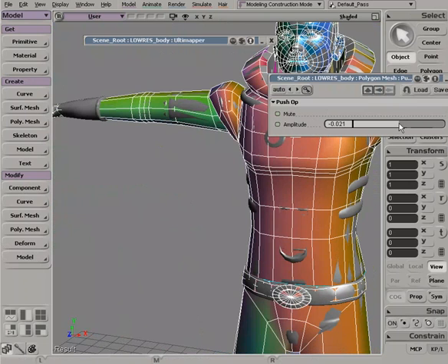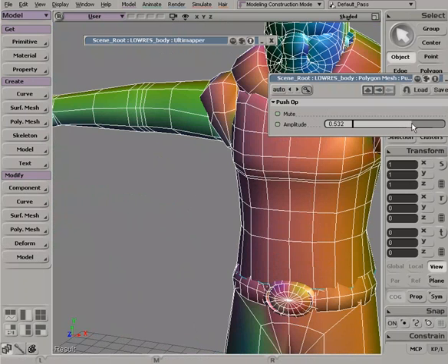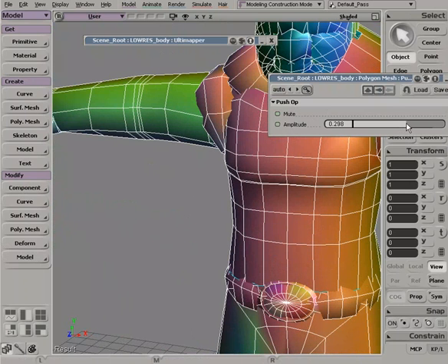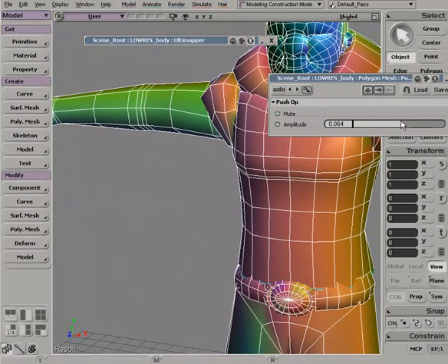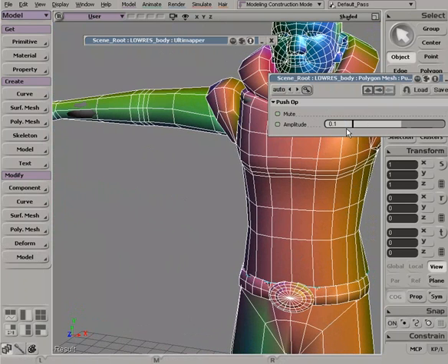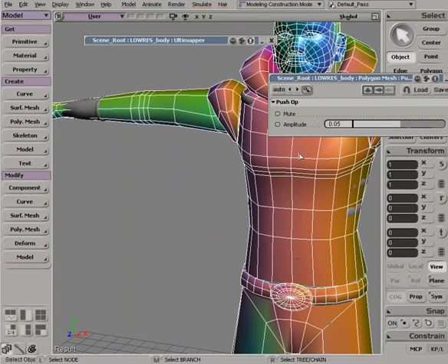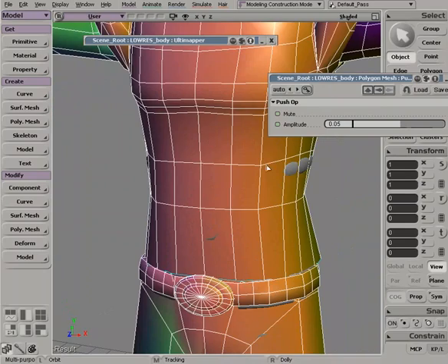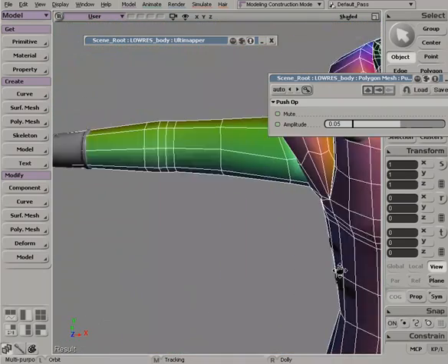With this Push Deformer, what it will do is pretty much inflate your mesh. You can see how that's slowly inflating this. So what I can do is just give this a really low value, like let's say 0.1. That's actually probably too much. Let's try 0.05. Just enough to be able to encompass pretty much all of these areas of detail that we're going to need.